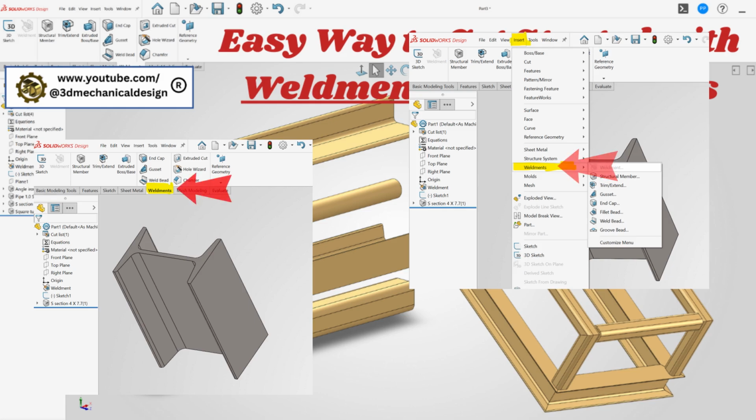If you've ever wanted to design frames, structures, or tables made of tubes or beams, this tool is your best friend. So what exactly is a weldment? In SolidWorks, it's a feature that lets you create structural frames using sketch lines and predefined structural profiles like square tubes, angles, or pipes. Instead of manually extruding each member, the Weldments tool does it automatically.